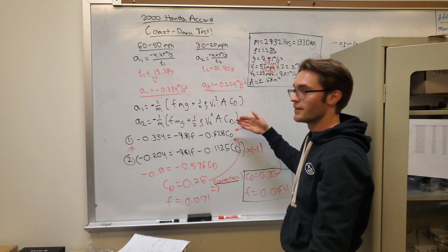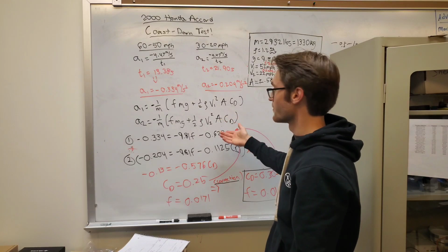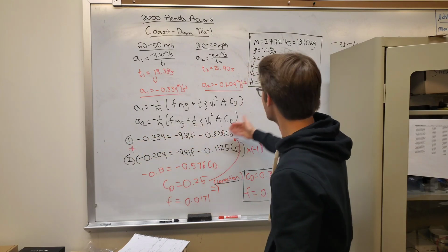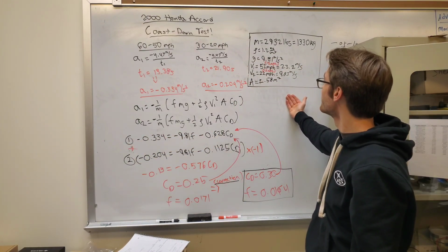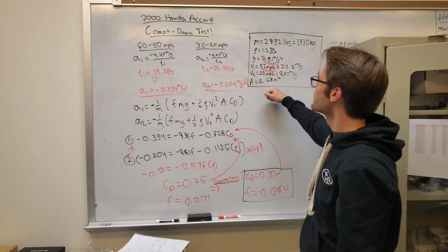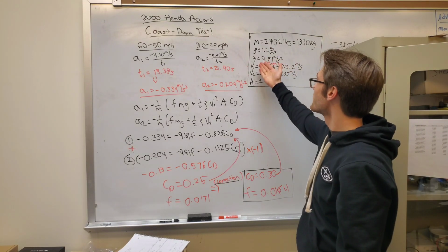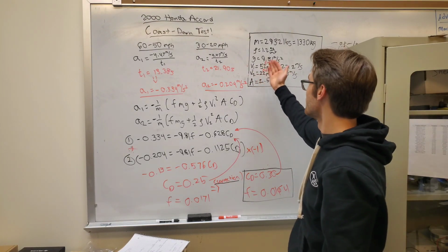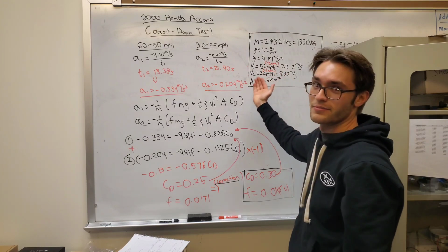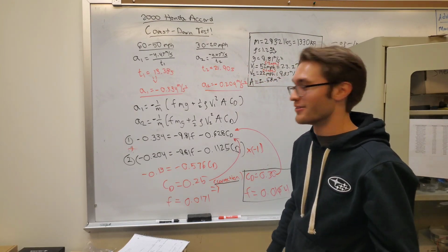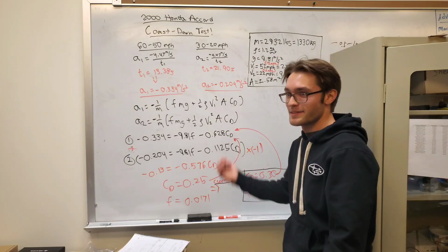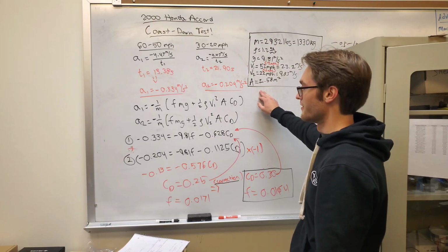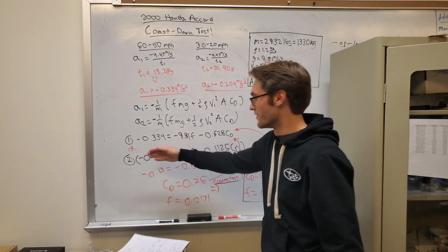Here's our road load equation minus the grade, because the road was assumed to be flat. We have our first equation while plugging in all of these constants that we have right here. We have our mass, our air density, our gravity, our velocities, and the reason why the velocities are not average, 55 miles per hour and 22 or 25 miles per hour, is because my speedometer was off by about 3 miles per hour. So compensating for that, we get our conversions here into meters per second, and we have our area of the car as well.